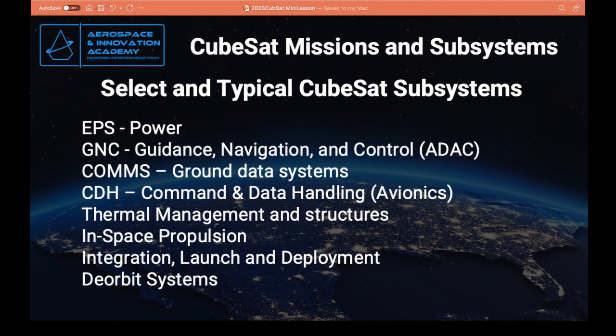There are three current technologies you can use to deorbit your spacecraft. One's called a boom, one is called a tether, and one is called a drag sail. They're all means to increase your profile. Even at 500 kilometers above the Earth, there are a few particles and solar pressure that push you down a little bit. So you end up losing orbit, but these tools will help you deorbit quicker. And they're important technologies in the future.